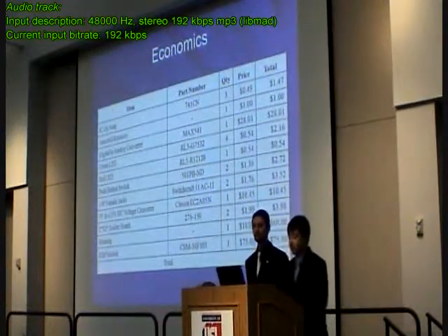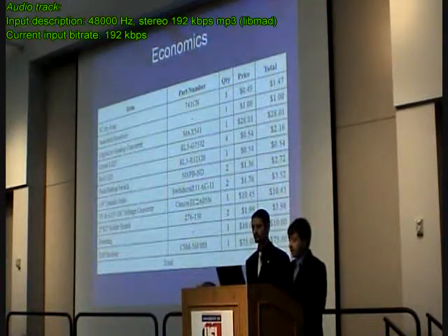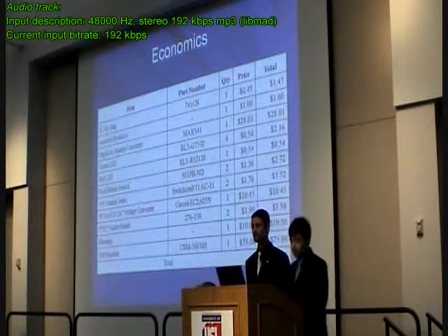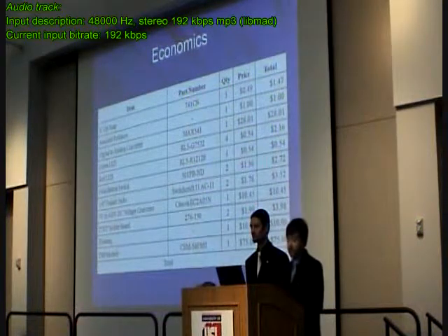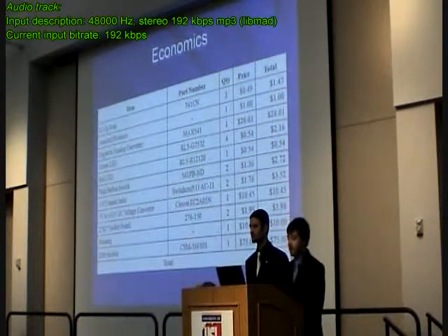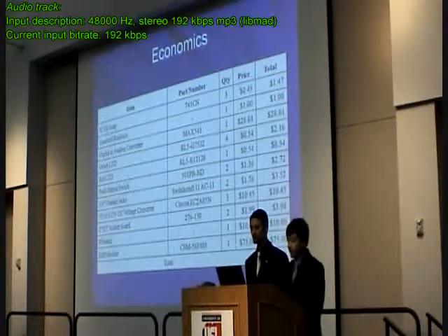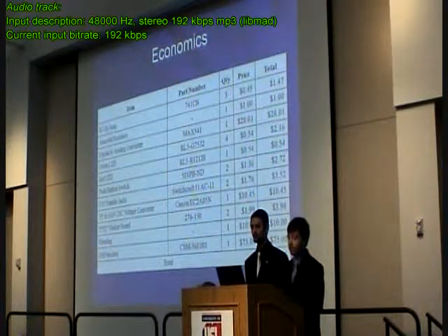The materials needed for a final product version of this project are listed in this table. 3 op amps would be needed to modify the input signal as previously described. Assorted resistors would be needed to control the gain in the op amp train. A digital to analog converter would be needed to output the signal from the DSP to an amplifier. 4 green LEDs would be needed to keep track of the key number of the filters.